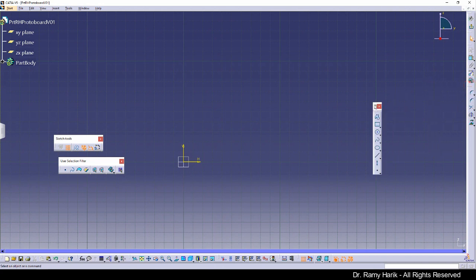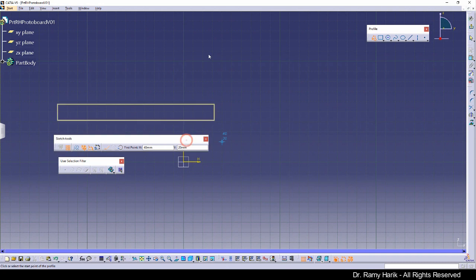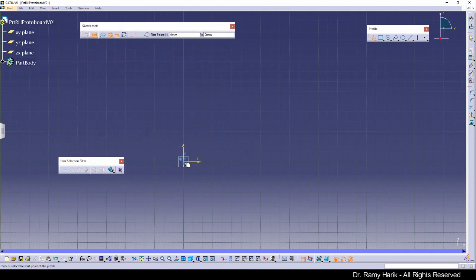Let me show you this. This is in the profile section. In the previous ones, we've done circles, we've done ellipses and so on. This one, the profile, is my absolute favorite. And this is the methodology that you should be using for design. So click on the profile and then start following how the shape approximately looks, with dimensions.